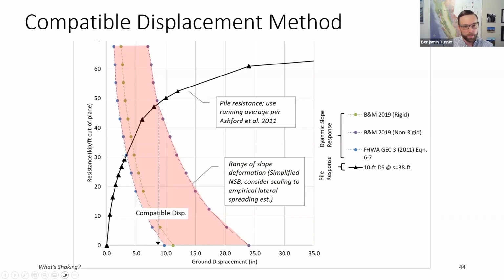The first one is the pile resistance as a function of increasing ground displacement. So just like you'd expect, when the ground displaces relative to the pile, we mobilize more and more resistance. You can see that this keeps going off the edge of this plot. Somewhere near here, the curve is kind of leveling off. So we're either approaching a flow around failure or structural failure of the pile would occur, probably a flexural failure. In fact, in this case, it would have been a flexural failure.